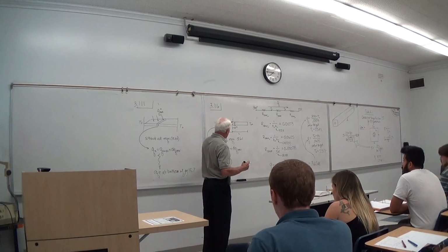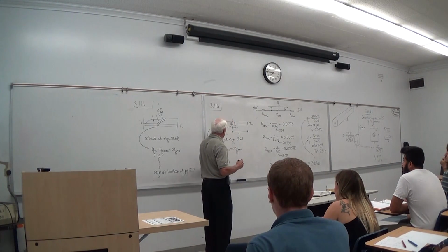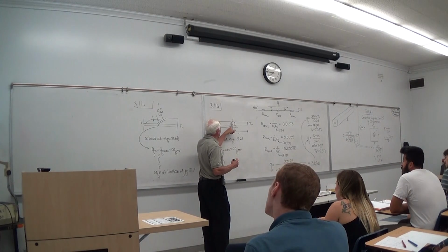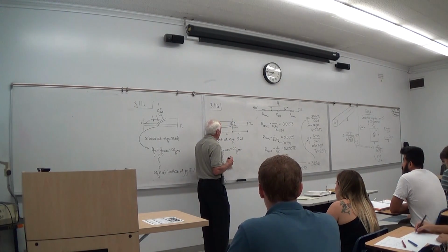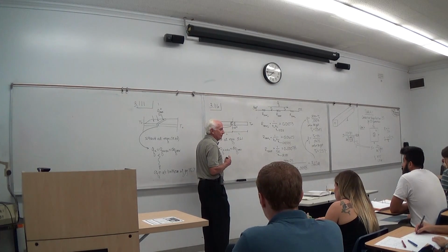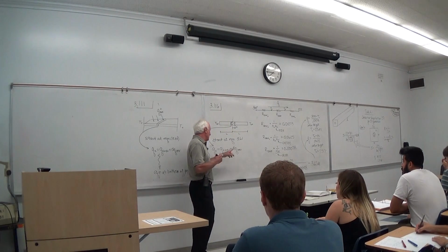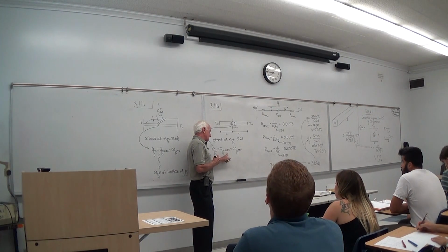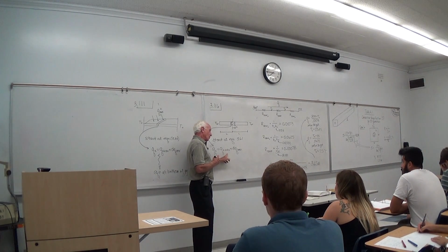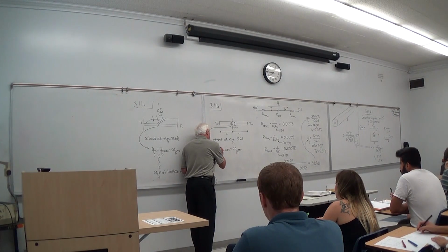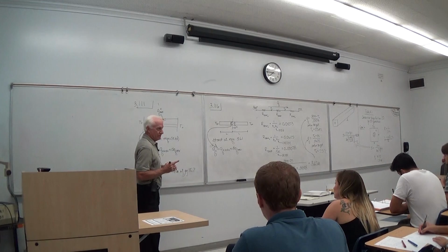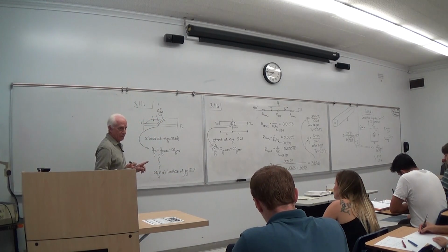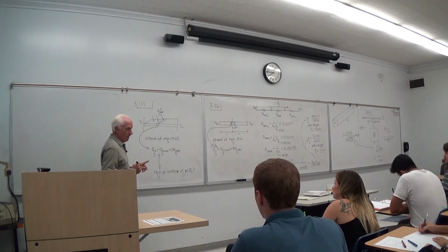This thing looks like the one back in the first part of the chapter, but now there's heat generation. Are you adding or taking out heat in the little element right there? You're adding heat. Which side of the equation does adding heat go on? I remind you, this side is all the terms which add heat to that little element, and these are the terms where heat goes out of the little element. We're adding energy, so you add Q dot on the left. Is it a constant? Of course it is. You're adding a constant to the differential equation. That's all you're doing.